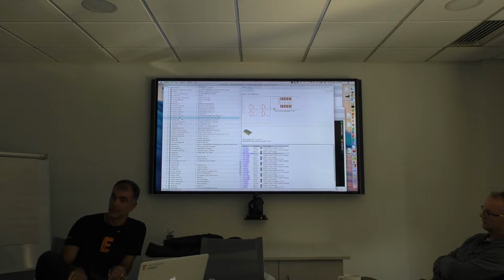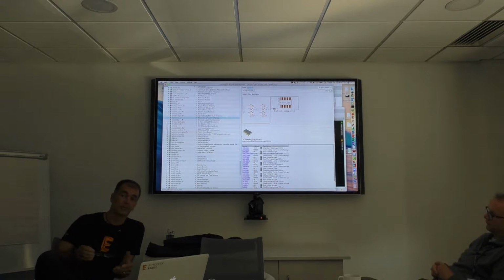This also can happen. But basically, yes, they follow an IPC standard, and I think you're good with it for all the normal designs. Of course, there are some exceptions: if you go to Siemens or Panasonic or the big companies, they won't use these libraries. They say we have our own standards. There we know that works with our manufacturing processes, and then they're good with it. So it's very difficult to have good libraries.